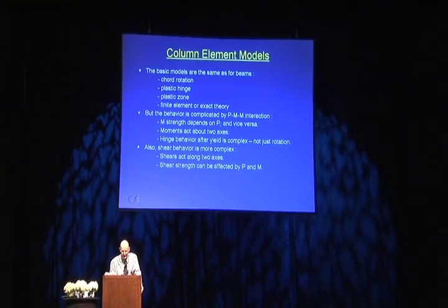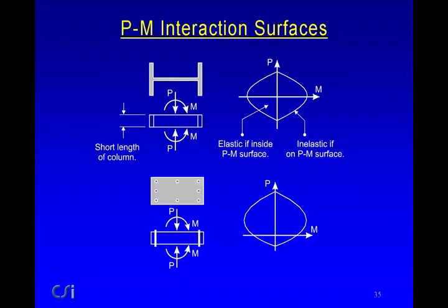The shear behavior is also more complicated. You've got biaxial shear, and the shear strength can be affected by axial force, by moment, and also by hinge rotation. So let's look at your PM interaction surface. You're familiar with these.